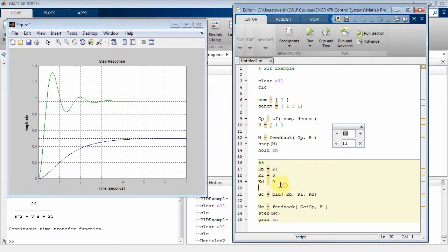Now let's go down to the D and start incrementing that guy. Well, a lot of people say we need to damp out these oscillations, but damping isn't really the correct term. Because if you remember, a periodic pulse train is a Fourier series with an infinite number of terms. Well, if you don't pass those higher terms, those terms that are up near infinity, what you're going to do is you're going to get ringing in your output. Because the really, really high frequency components are being filtered out on a perfect edge.